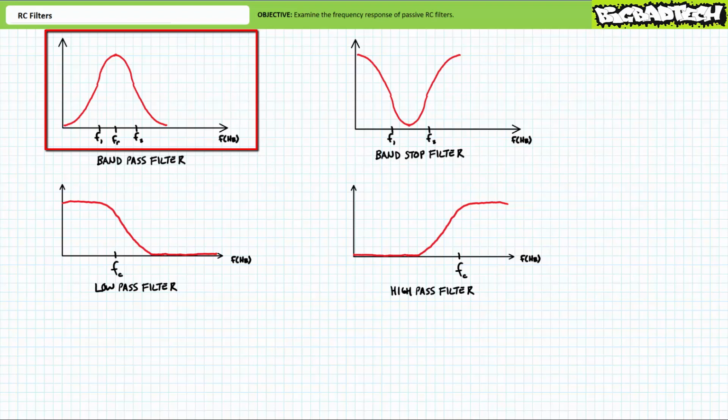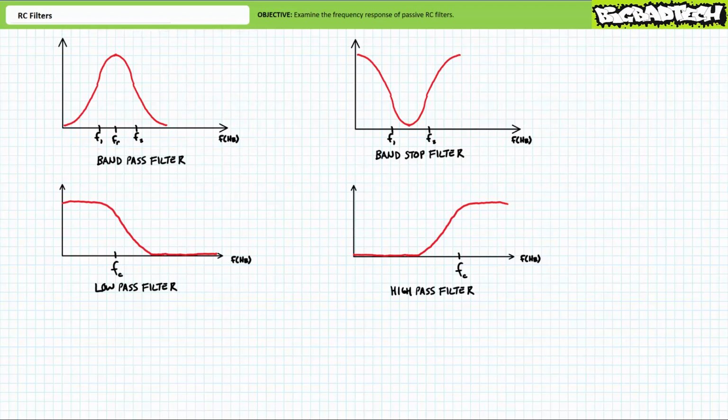You'll recall in the Resonance lecture, we learned that source current through a series circuit peaks at the resonant frequency, FR, and inside a specific bandwidth defined by the lower and upper half-power frequencies F1 and F2, the circuit experiences half power or greater. If you want to think of it in this fashion, a series resonant circuit is a type of filter, specifically a band pass filter, whereby frequencies inside a particular band experience more output and frequencies outside this particular band experience less output.